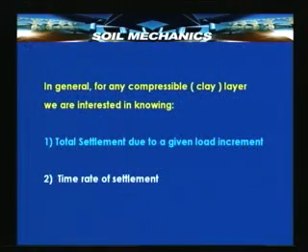In general, for any compressible clay layer, we are interested in knowing 2 things. One is, when you construct a building, you have to design this before it is erected, keeping in mind the possible consolidation and settlement effect, which means that we are essentially interested in knowing how much settlement, or in other words, what is the total settlement that the building is going to undergo over its lifetime when it is constructed over a given saturated clay soil layer of finite known depth.